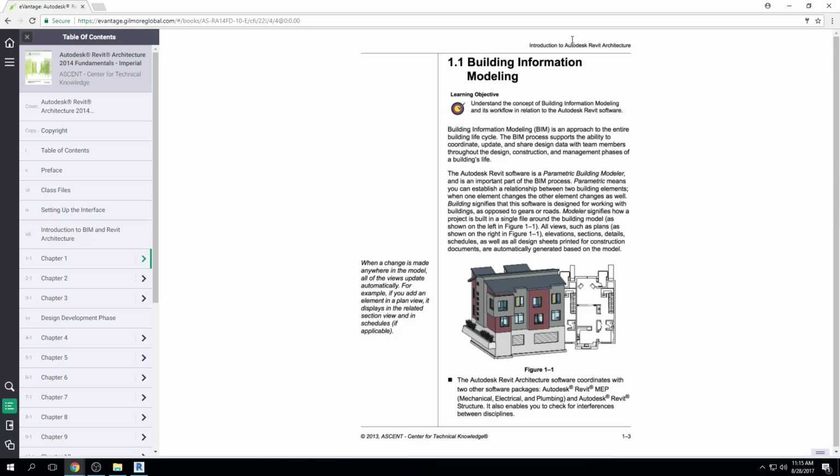When I work with AutoCAD files, I take all of these individual files, and number one, they all correspond, right? I use the floor plan to generate the elevation. I use the floor plan to generate the section. I coordinate the elevations and the section so they all look the same. And then when I create sheets over here, things like A101 or A201, I use XREFs to attach or connect these things. So I XREF the floor plan into this sheet and I get A101, which shows the floor plan. Great, okay?